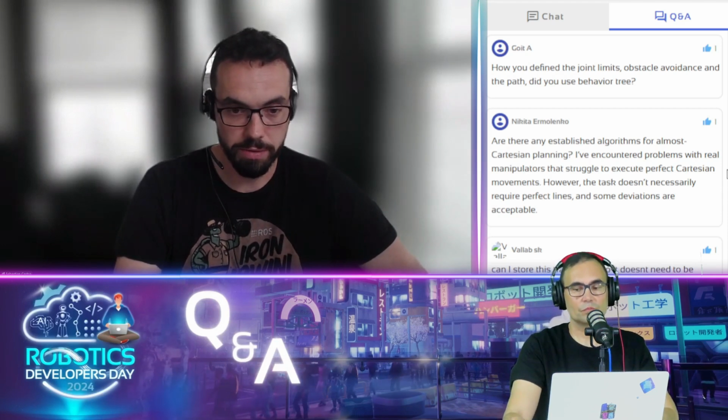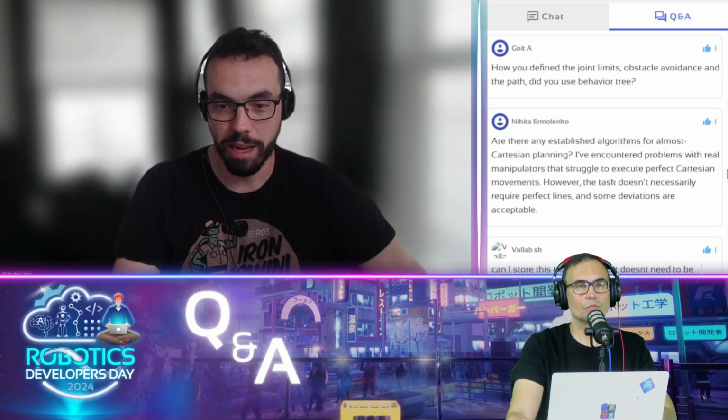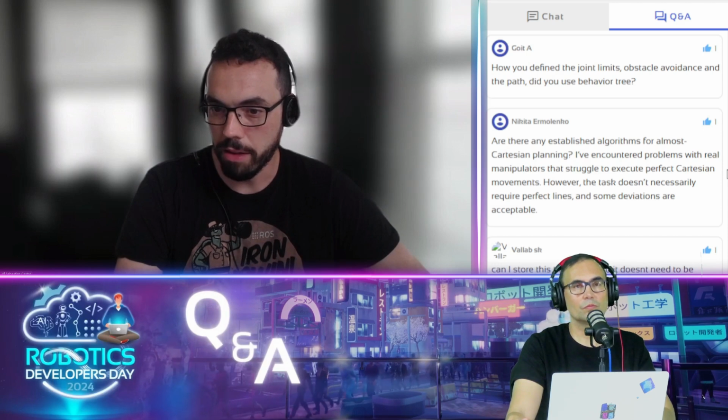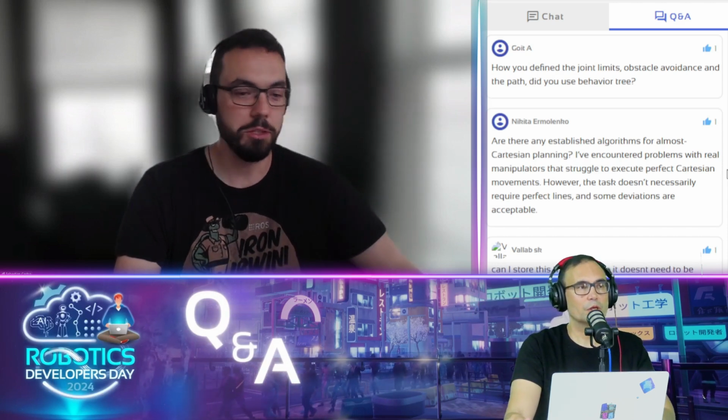As far as the joint limits and obstacle avoidance, these can be defined in two different places, right? We talked about the URDF description. If I look at the UR gripper as one example, you see that all of the links that you create in your URDF actually have collision geometries that could point to things like meshes or geometric primitives like rectangles. See here, somewhere in here you have collision boxes for the gripper, for example. That's one way. URDF also has a way to load some joint limits. If I search for a joint, for example, you see here the wrist2 joint has certain limits encoded for it, for maximum effort, position, and velocity.